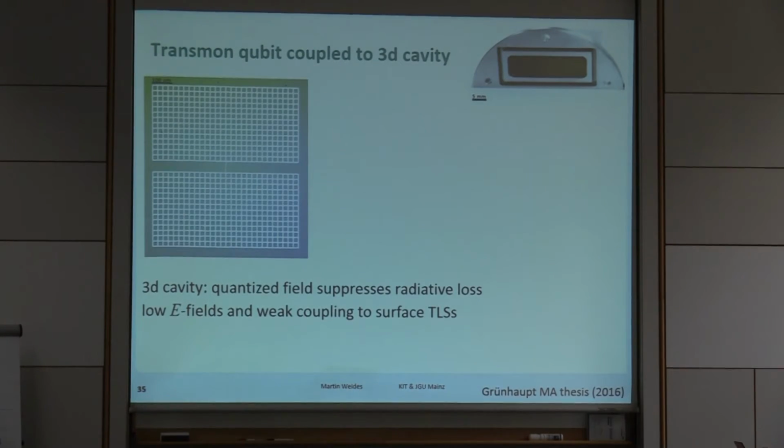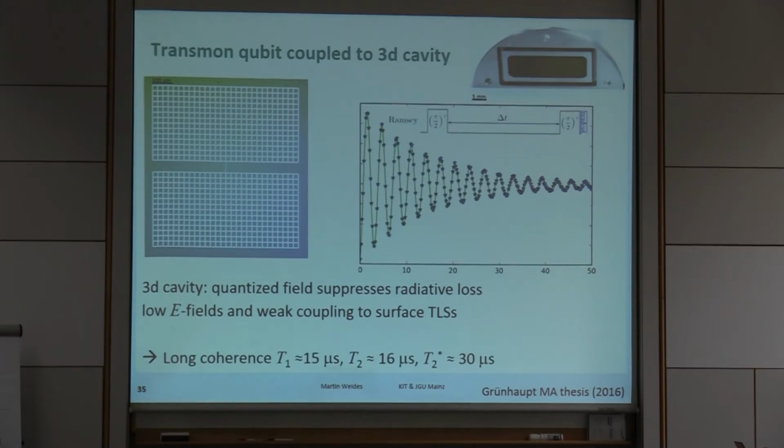So we also have 3D transmons in our laboratory. We made them for a different project, but they're available. So that's a sketch, a micrograph of the circuit. Here's one junction, just part of the cavity. We did time domain, Ramsey and T2 measurements, T2 star measurements. That's the Ramsey data we've taken. On the first sample, we had about 50 microsecond coherence, and T2 star about 30 microseconds. So it's a well-behaved 3D transmon chip.